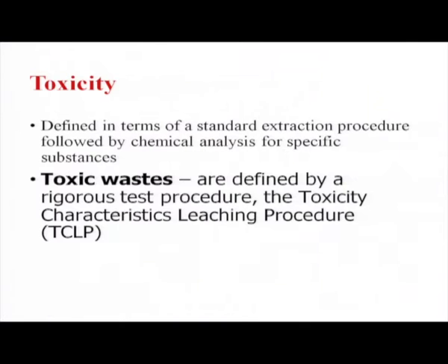And the fourth property, a very important one especially from the environmental angle, is toxicity. How toxic these wastes are, and this toxicity is defined in terms of a standard extraction procedure followed by chemical analysis for specific listed chemical substances which are all highly toxic in nature. And toxic waste is defined by a rigorous test procedure. Okay. The toxicity characteristic leaching procedure is the current one. Earlier also, EP toxicity, extraction procedure toxicity, was there.